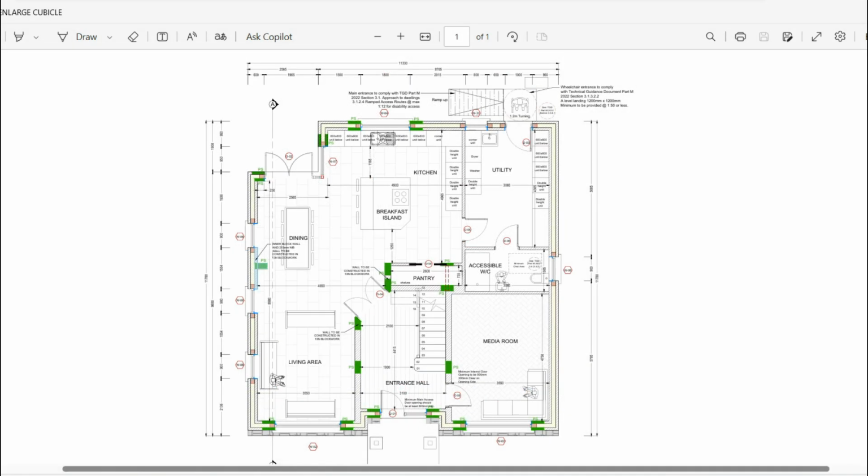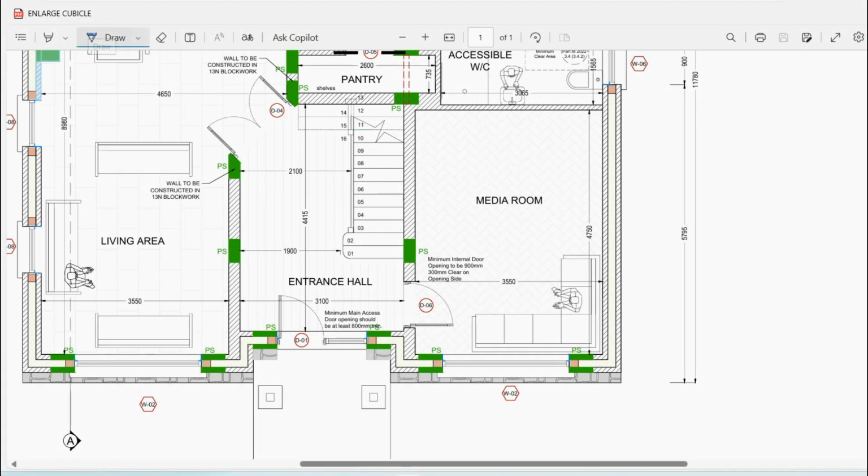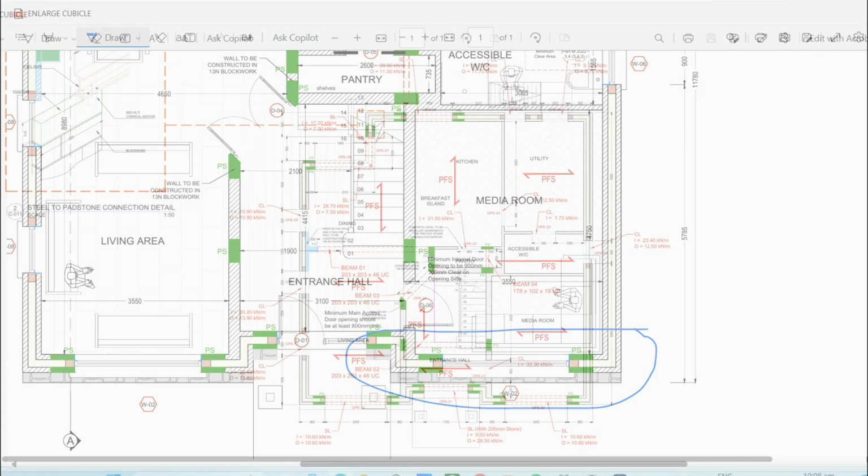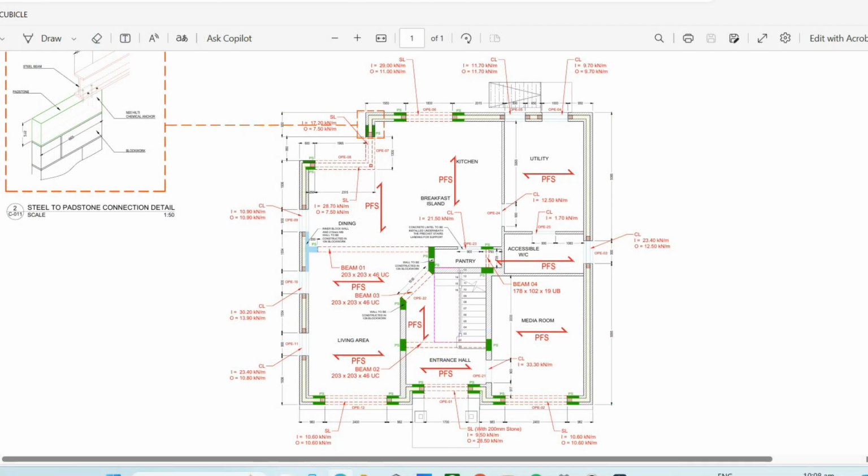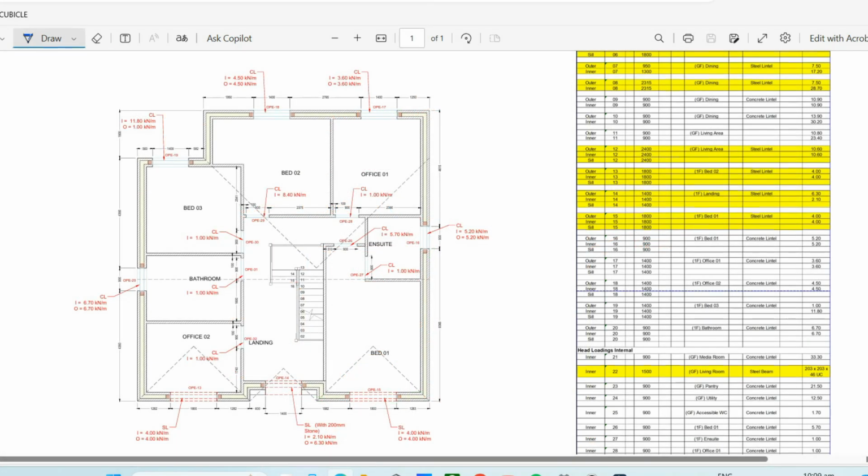As we can see on the floor plan, we would draw up this padstone onto the floor plan, and this will either need a structural steel beam or steel lintels. If we take a sample house here, a ground floor plan, it is marked up with the directions of the precast floor span and shows the loadings that will come down, internal and external.